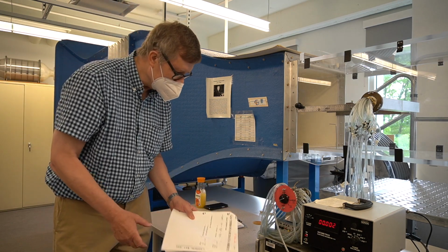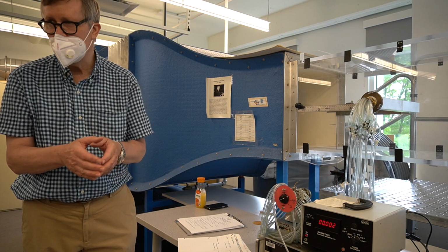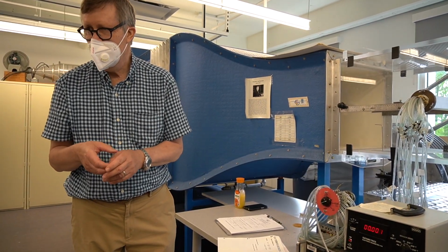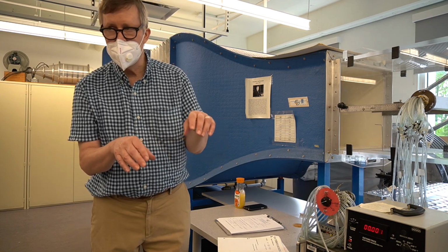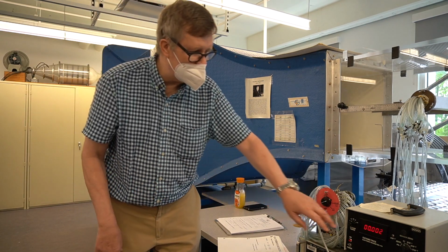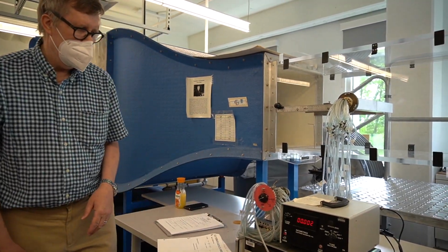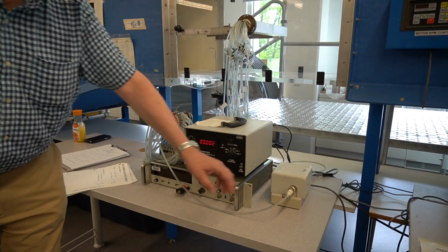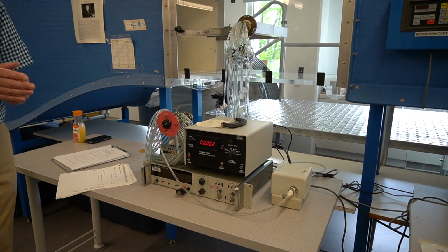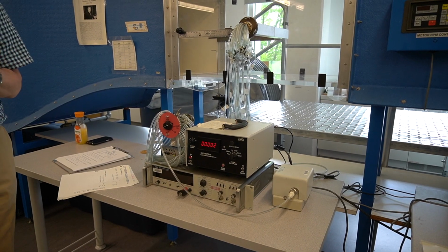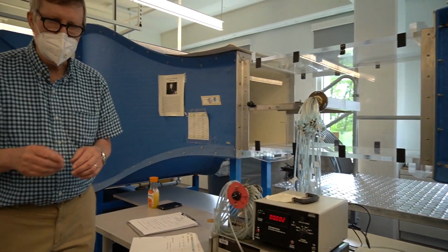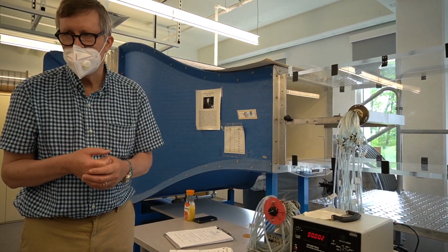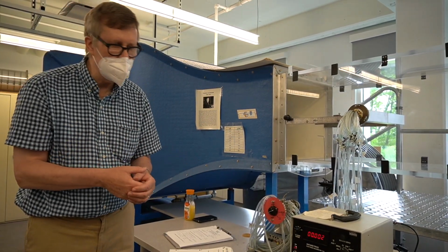And so when you actually measure a pressure coefficient, you measure P minus PS, and you divide by half rho U squared, but that's the same as PT minus PS. And all these things, P minus PS, PT minus PS, they're just voltages that are coming out from the front of the transducer here. This thing is the pressure transducer. Just to let you know, there's a little diaphragm in there that is able to get pushed one way or another due to differences in pressure on each side of the diaphragm.